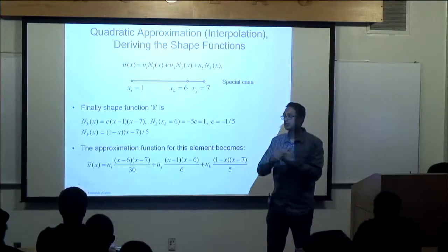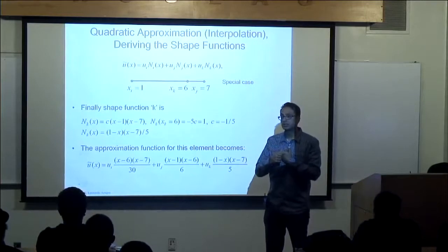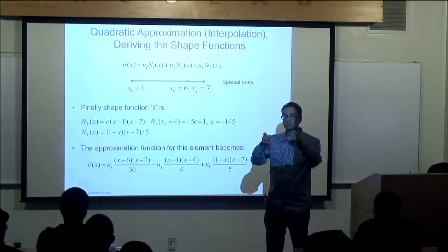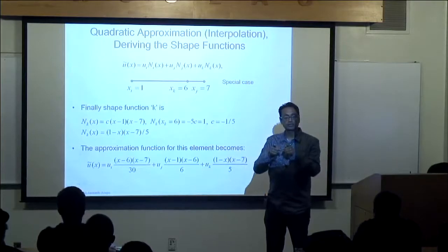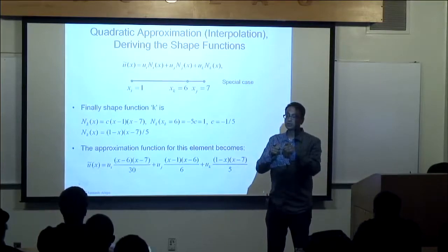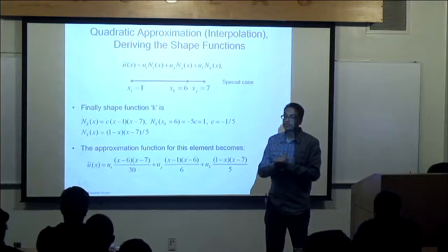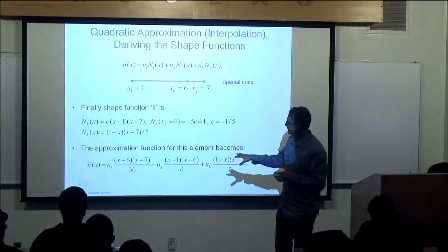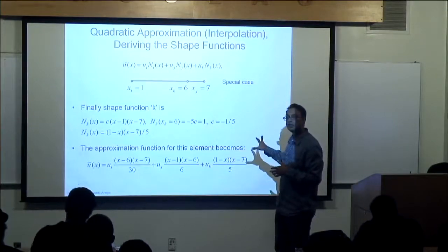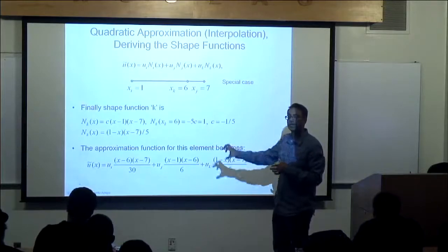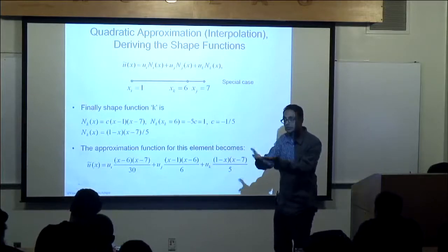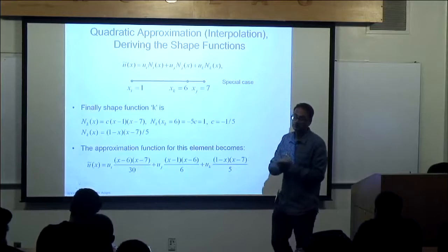To have completeness, we should be able to represent rigid body motion. We showed that in the last lecture. And then we must be able to represent constant strain rates, or constant temperature rates if you're looking at a heat transfer problem. So the physical meaning is that they are more mathematically formulated to allow you to accomplish things you could not do before in that manner.